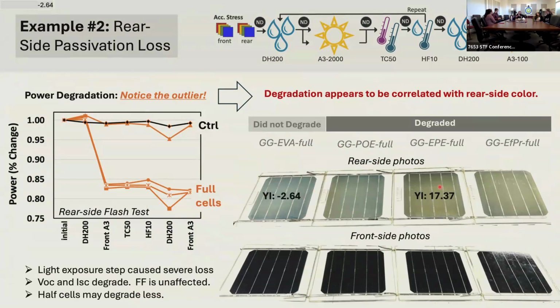Okay. Question from Takeshi Taigaki here. Are all the images you showed taken from the front, and do you see any difference on the back? All the images shown here are from the front. We take the images on the front and back every single time, so we have too much data sitting around. That basically tells you it's not that useful. The rear side images look basically the same. The usefulness of taking the images from the back is to see the metallization pattern and how the degradation is related to the different shapes of the metallization. But in terms of recombination, the recombination happens within the silicon, and because of the thickness of the silicon, you're not getting much difference in the pattern of the luminescence depending on what side you measure from.